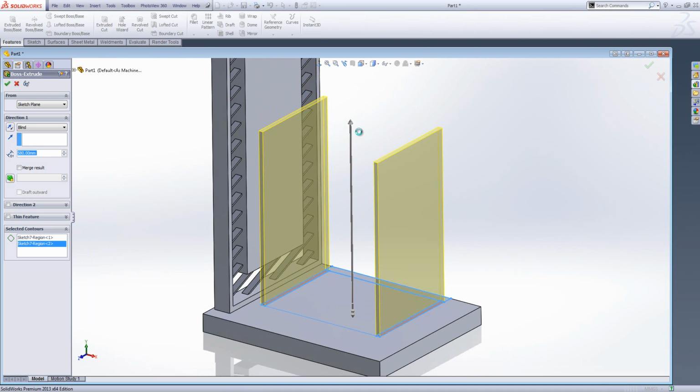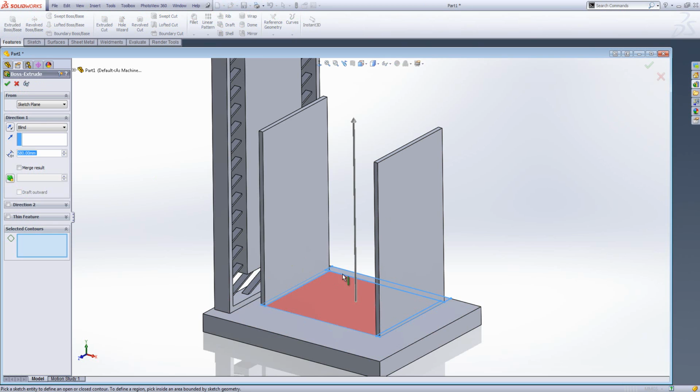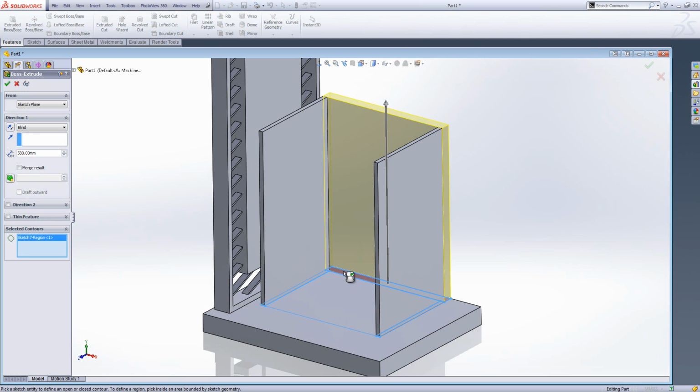Okay, there we go. Once we're at that value, we can select the sketch again from our left hand side, just grab it from the design tree, and then use the extrude tool again to select other areas and extrude those one by one. Again you'll notice merge results is turned off, so each time we create the elements we end up with different bodies being built.